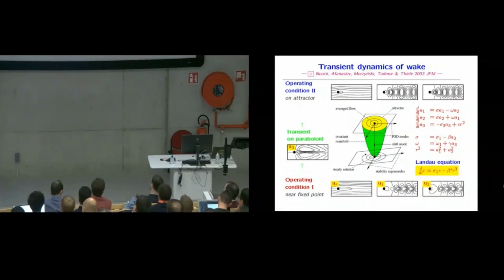So what happens? Well, we have a nonlinearity. More precisely, we have a Reynolds stress. And the Reynolds stress changes the base flow. So as the fluctuation moves more and more up, the mean flow becomes shorter and shorter. So this bubble is eaten away by the Reynolds stress.